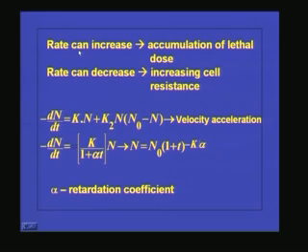And now we can see that, okay, as we have seen till now, the rate is a constant, but rate can increase or rate can decrease. When the rate can increase, for example, initially the concentration of the disinfectant is less, okay, with respect to time, what is happening? The microorganisms are there in the same water and the disinfectant is there in the water. So what will happen with respect to time? The chemical or the disinfectant will be getting accumulated in the cell wall. So it will be getting accumulated, and at a certain stage what will happen? The concentration of that chemical will be exceeding the maximum permissible concentration which the body of the microorganism can withstand. So what will happen? Once that concentration is reached, the microbial destruction rate will be increasing.